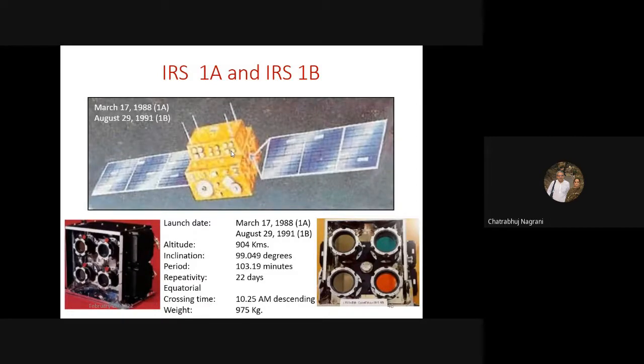So when you have higher resolution, what happens is that because you are using the same strip of the sensor, it will cover a smaller swath. So suppose this has a resolution of 70 meter, and this one say 35 meter. If I put 2, then 2 together will give the same area as 1. So 2 high resolution cameras and 1 low resolution camera.